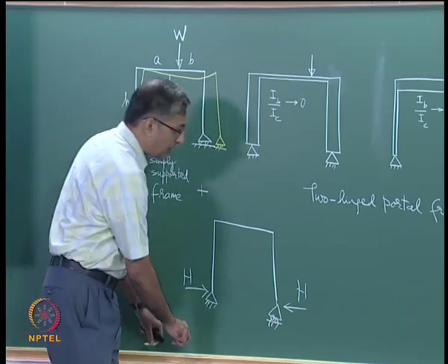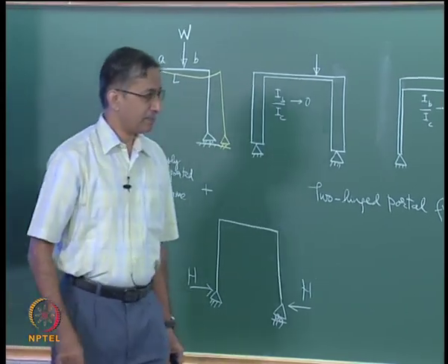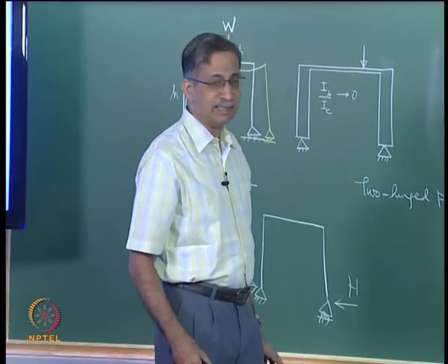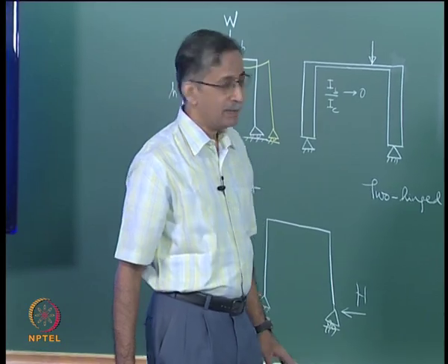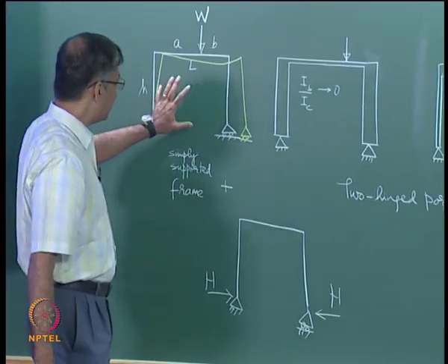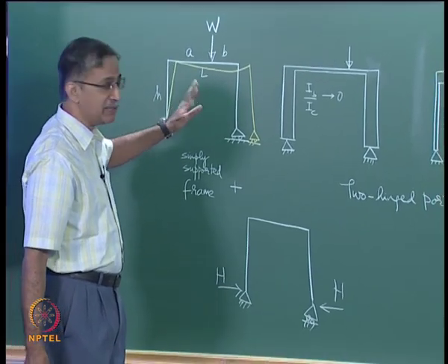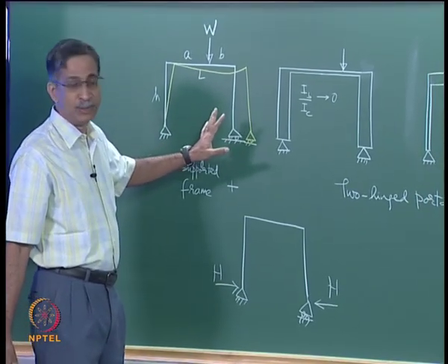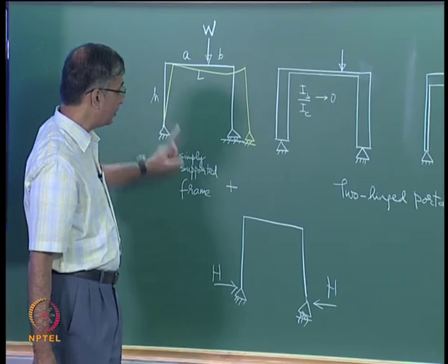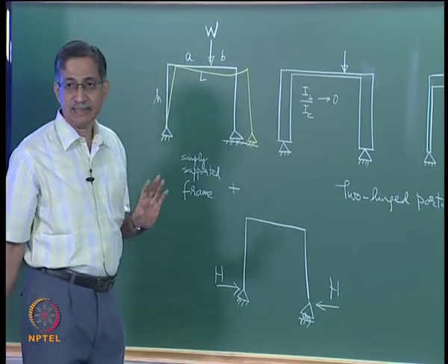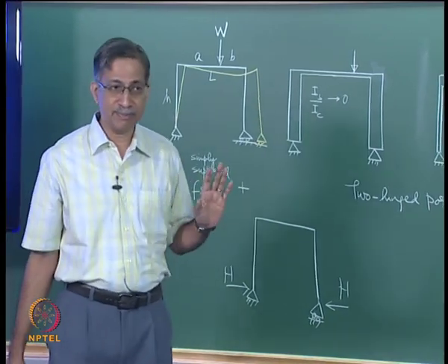Now how do you analyze this frame, how do you understand its behavior? As far as the bending moment diagram of this frame was concerned, bending moment, shear force, axial force, you will find that the force response does not depend on IB and IC, does not depend on the relative stiffness of the members.